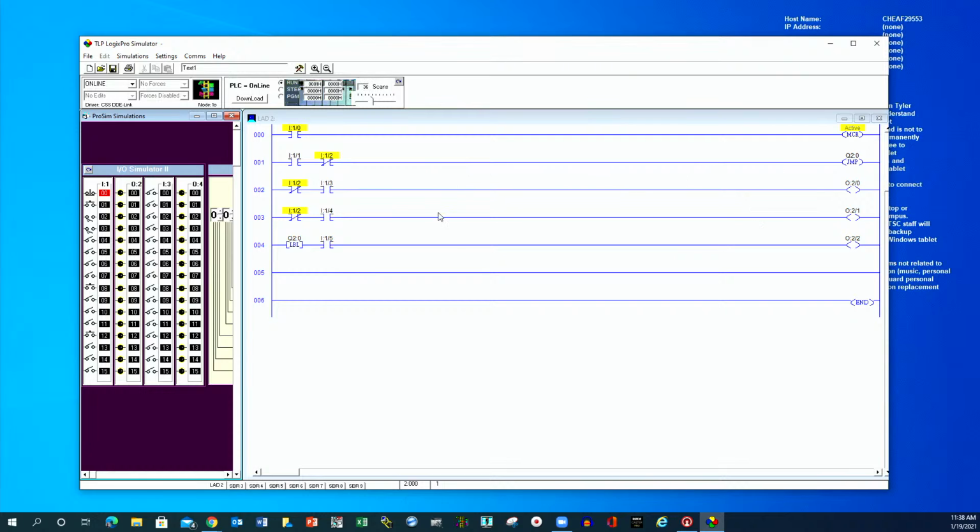But the MCR fence means anything within here is now working. So if I click on 3, you can see rung 2 come off and on. All right, let me flick it over to a maintained right there. Let me do one more so I can do a couple things at once. If I click again, there's 2. Let me take 2 and open that up. Oh, I need it maintained. There we go. That is going to allow us to do something within here, right? That means all these are now active. They can come off and on, and they should work.